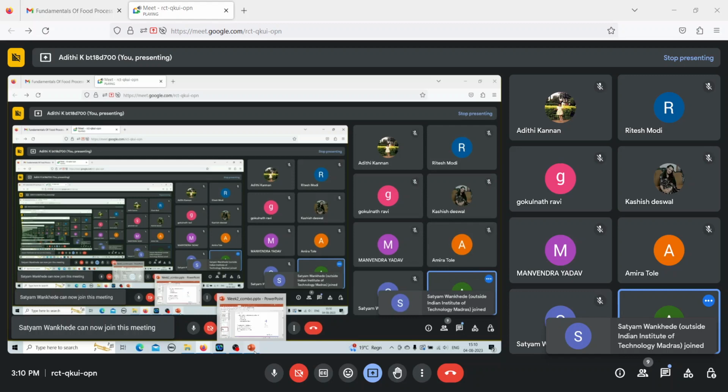When you pull apart here, both will experience an equal amount of strain, but the stress will be summed up. So gamma of spring is equal to gamma of dashpot, but tau is equal to tau of spring plus tau of dashpot. Is this clear?